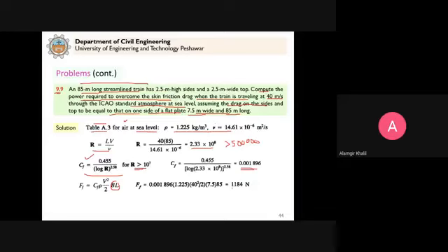This is the friction force. So this is equivalent to that acting on a train. We calculated for a flat plate, and this is equal to that acting on a train. And then we know that power is equal to F into V, force into velocity. So power will be equal to force into velocity. This is the power required to overcome the skin friction drag.